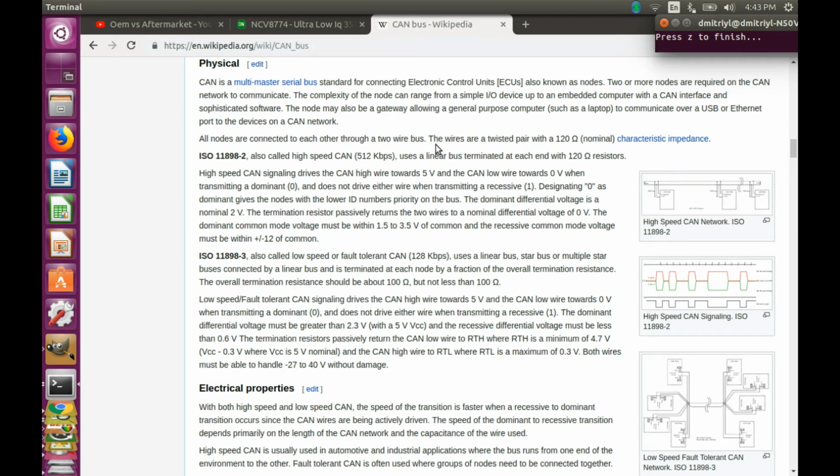Many CAN bus faults can be diagnosed by connecting an oscilloscope to the bus wires and observing the waveforms and messages that are flying across the network. However, certain faults, such as intermittent wiring faults and loss of one of the terminating resistors, are harder to spot. Also, sometimes it's necessary to perform diagnosis on a powered-off CAN bus.